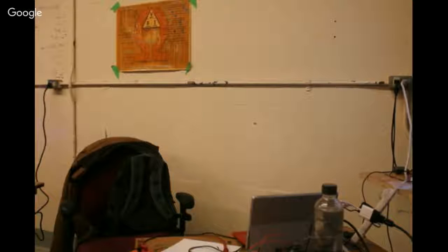So the main thing is the connection from the color back down to ground. And so it's this move from the power supply, 12 volts through, and then the return path through these guys going to ground is controlled by transistors. Because you always need two sides to a circuit.